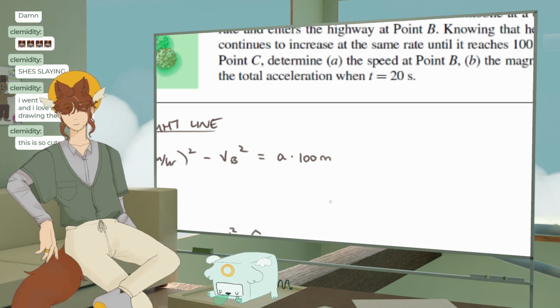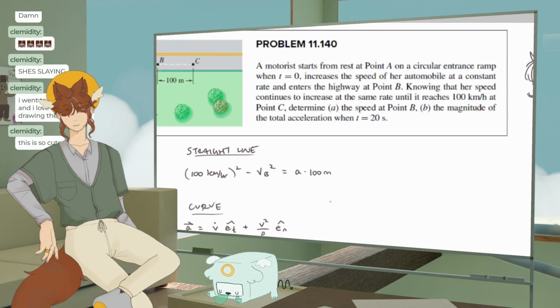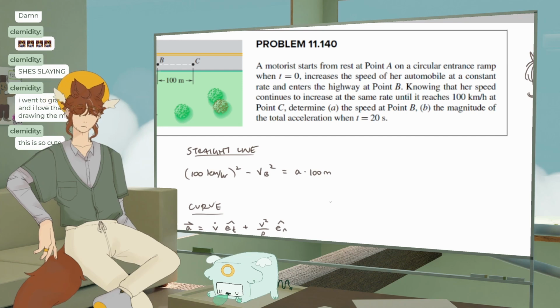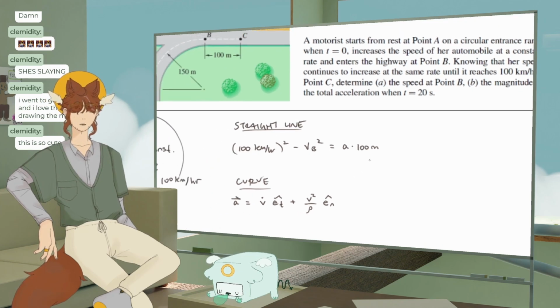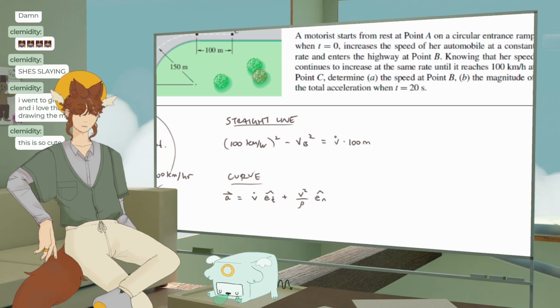Actually, so the V squared over rho is due to the turning part. So when we turn, we're getting V squared over rho, and we're adding that sort of onto our other acceleration. But our tangent component is only this V dot. So really when we say this, we're only saying this. I really shouldn't say A, this should be V dot. So now, and we can...